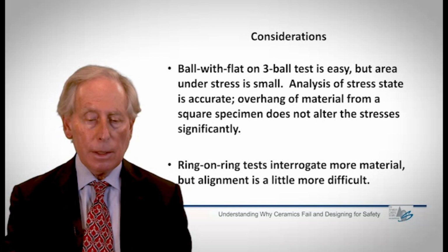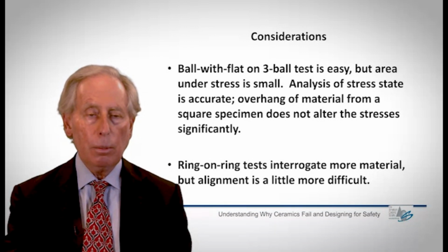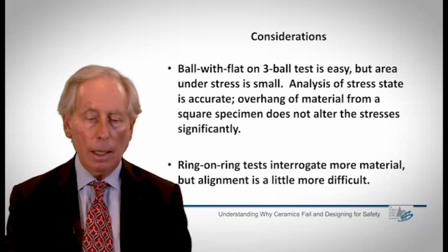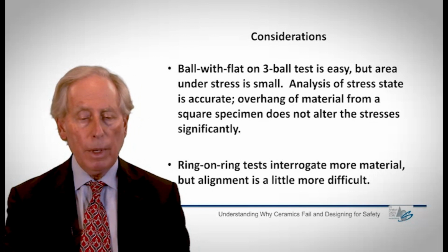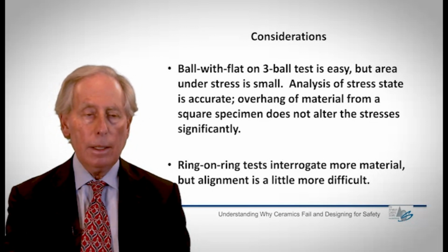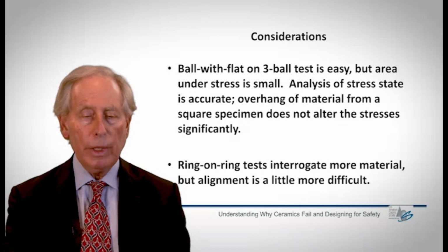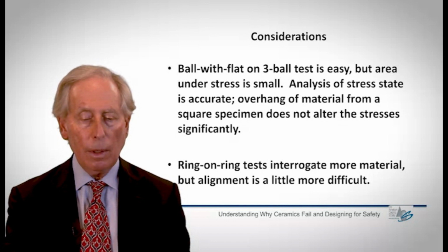Ring-on-ring tests interrogate more material because there's a larger area of your disc or plate under stress in those tests, but the alignment of the particular test is a little more difficult. The choice will depend on what kind of equipment you have, how accurate you need the measurement to be, and how big the plates are. But this gives you a flavor, between two kinds of tests, of what sort of procedure you should use.